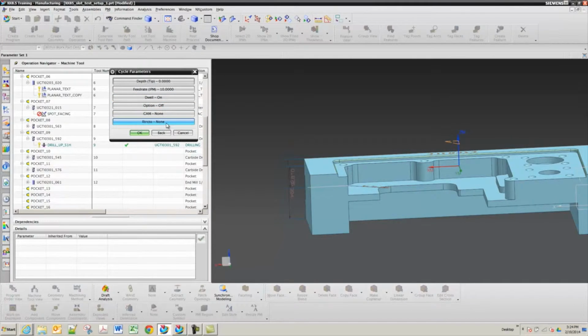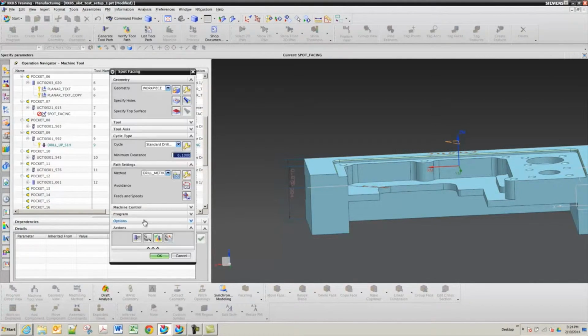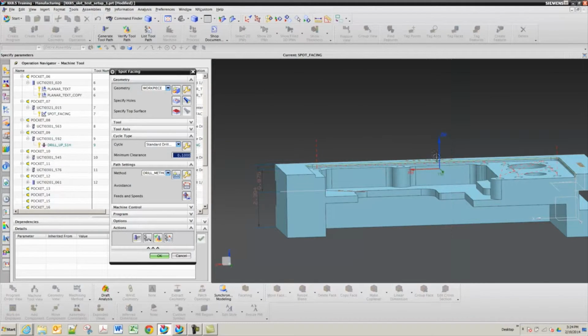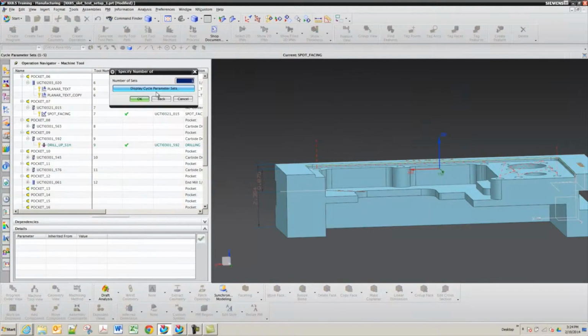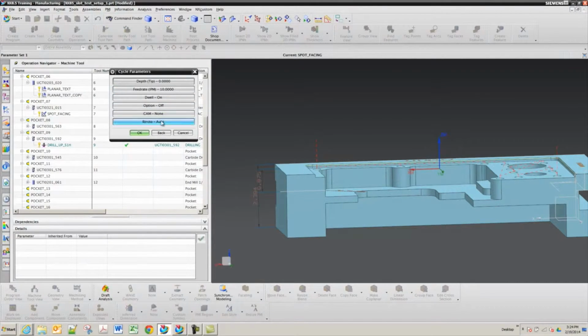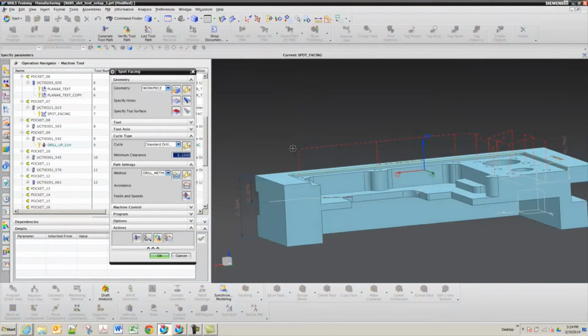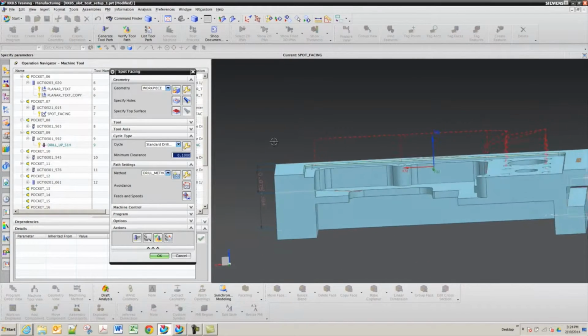Go into retract. Well, I'll show you before I do the retract. So I'll generate it, and so it went up, but it's transferring it to lower. Okay, so that's why I was going in here. So I have to go into edit, OK, retract, set it to auto, and then say OK, and now it's going up, but it's not starting the cycle.